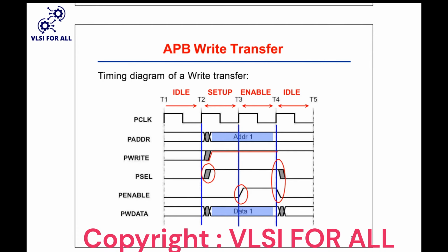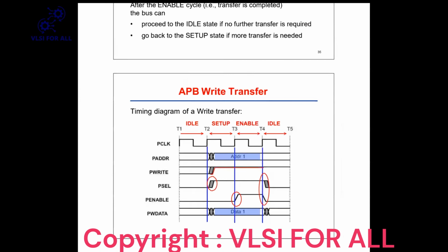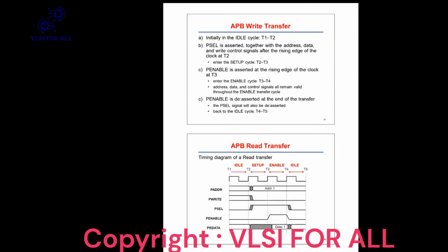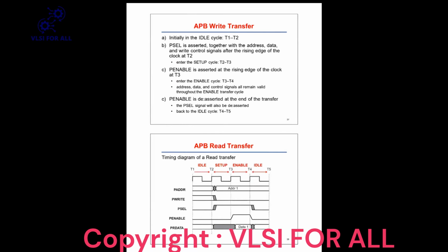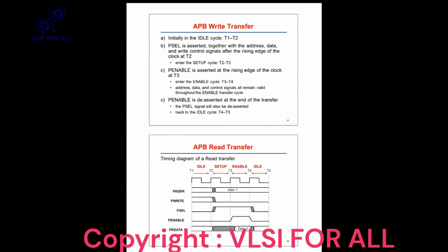That's why they have considered directly that the slave is ready, and now they are driving the data. It shouldn't be like that if you are going with wait state, but this is a diagram without wait state, so it's fine. But mostly we go without wait state only. So the without wait state concept must be understood.